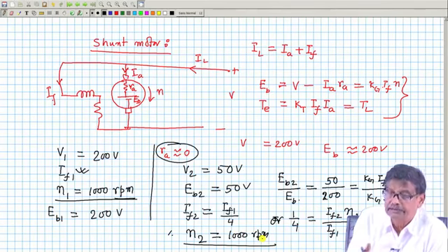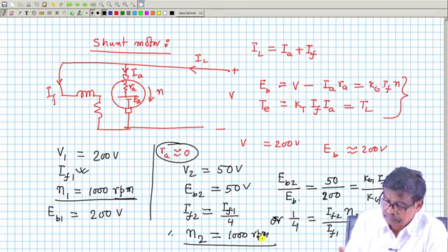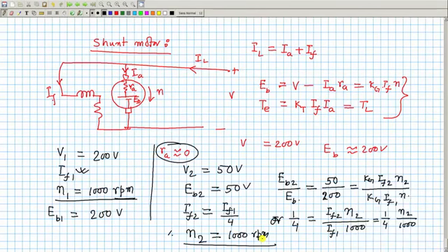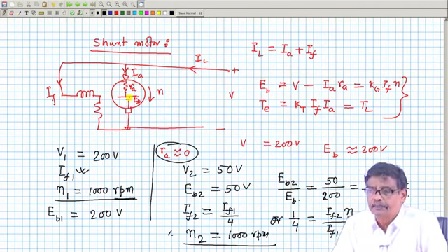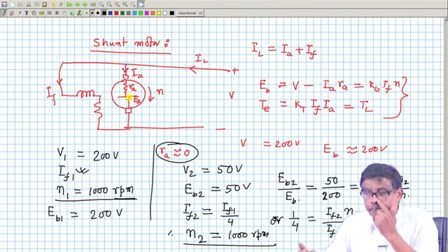And from this, the load torque does not come into the picture provided RA is equal to 0, but it will definitely come in if I have to take the equation of torque. There I do not have to write the torque equation, I am getting this as it is. So, V minus IARA. So, often to get quick results, you neglect RA and quickly calculate, and back EMF will remain the same. Got the point?